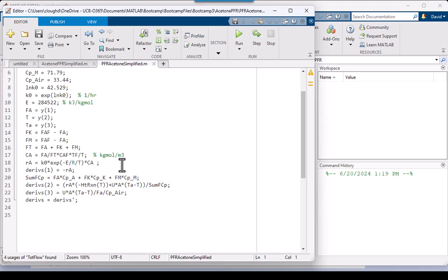And then we have our derivatives. In this case, we do not have any algebraic expressions that we're trying to solve for along the way. We've not done it that way. We only have derivatives, and for that reason, we don't need a mass matrix, and we don't have to use ODE15S along with that. So we used ODE45, a conventional integration scheme.